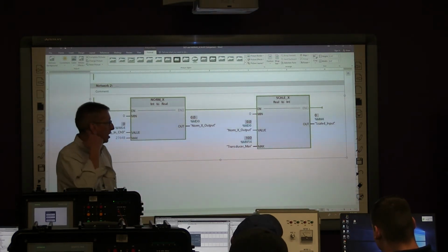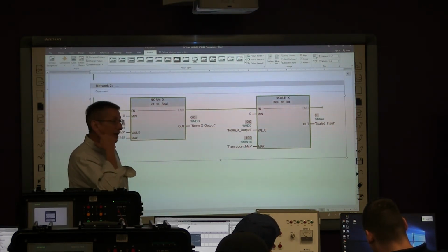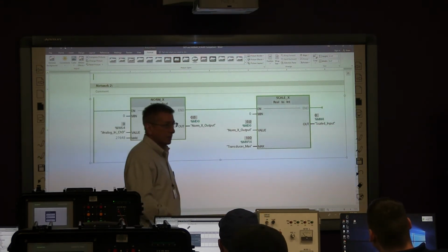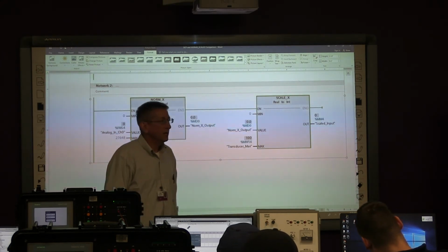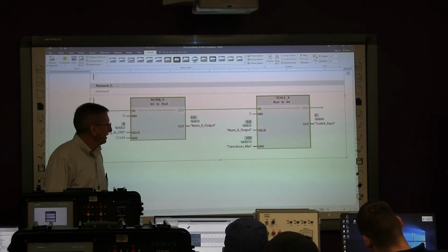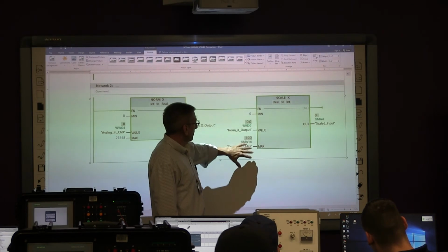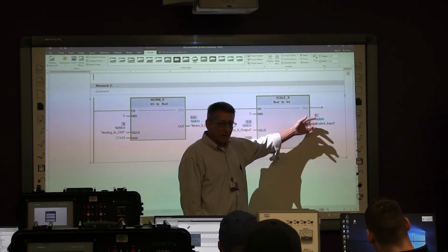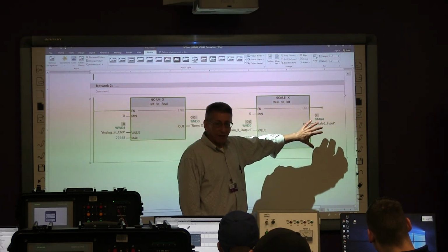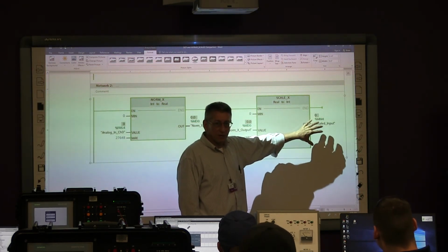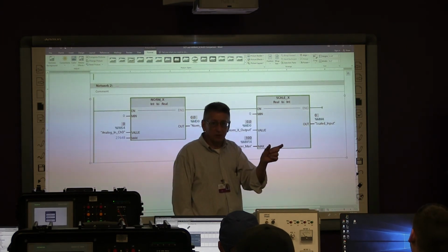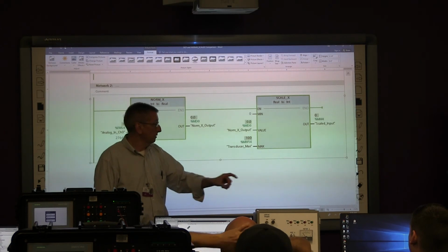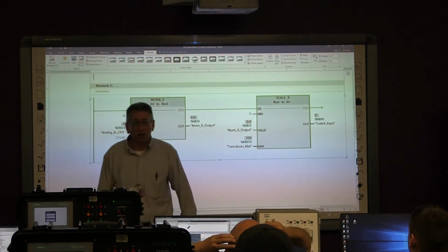Where will you use that output? That'll go to your meter? Yeah, that'll go to an output, where you'll move that MW4 to the output 80. Whatever, 75%. Once we get done scaling, we're going to have 0 and 100 out here, and that might be used on an HMI. You grab this data out of the PLC with an HMI, a display object, and that's going to be the input to the HMI.